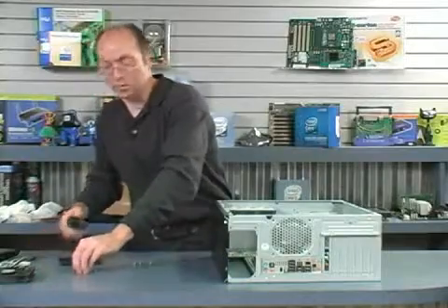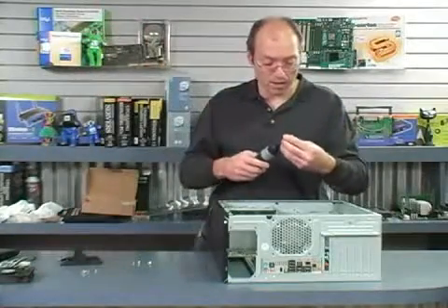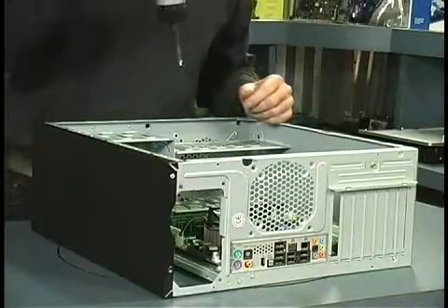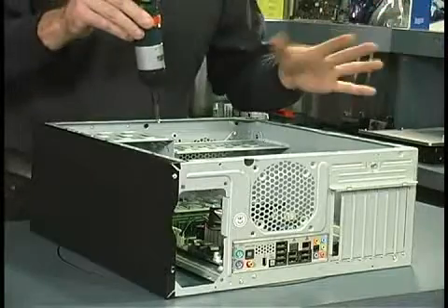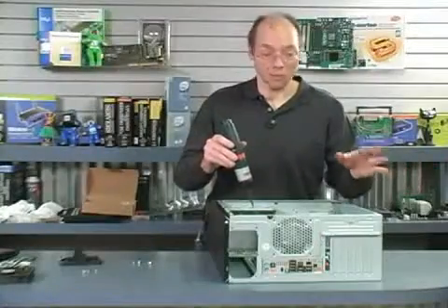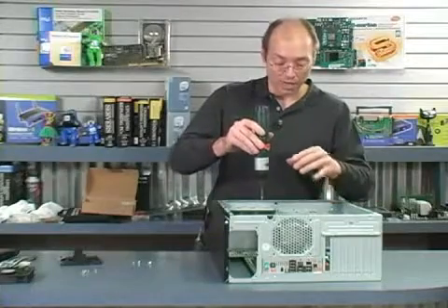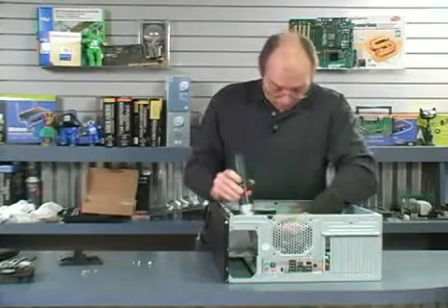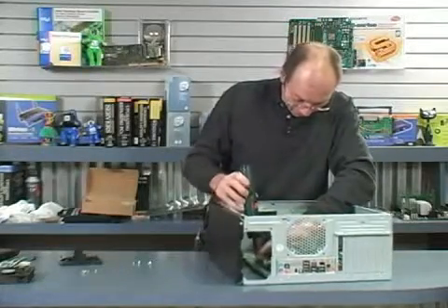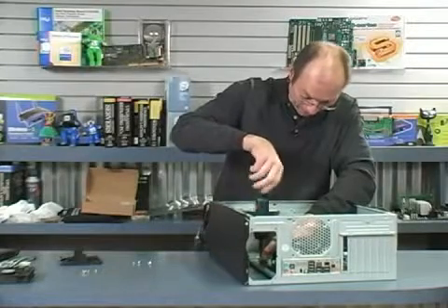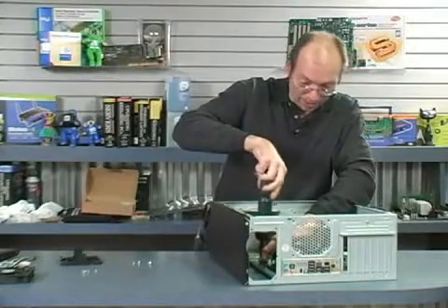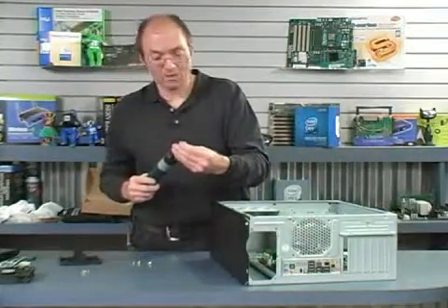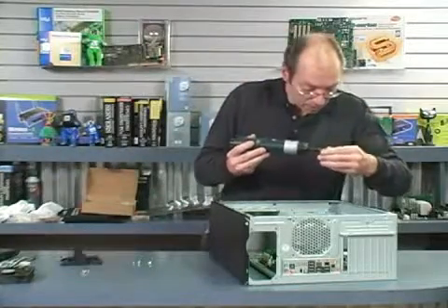Now I assembled 9 screws from the little hardware bag that came with the case. And one thing I wanted to point out here, notice I'm using a magnetized screwdriver. I think it's a requirement when working on PCs. In fact, Intel recommends it as a way to prevent damage to motherboards, because it keeps the screw in the tip of the driver and prevents it from walking out. So a lot of people say you shouldn't use magnetic tools around a computer, and I beg to differ. I consider it a necessity when working on a computer. It doesn't cause any harm to any of the circuitry, so it's not a problem.